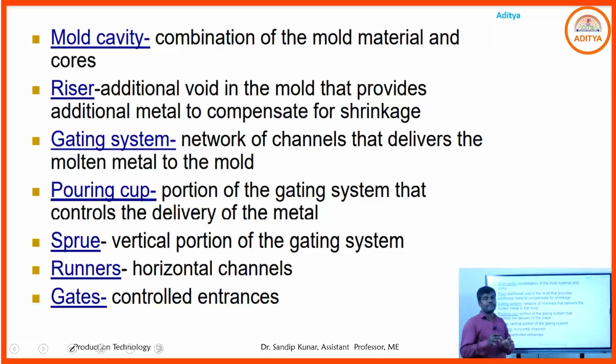The riser acts as a molten material reservoir. It is an additional void we prepare in the casting process. When the molten material comes into the mold cavity, after some time it solidifies. After solidification, some voids are created due to shrinkage. Due to that void creation, additional molten material comes to the mold cavity to fill up those voids.